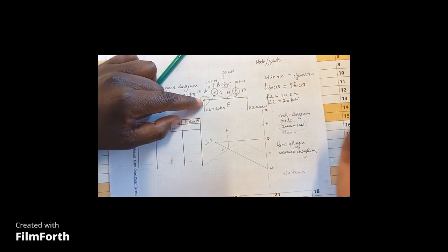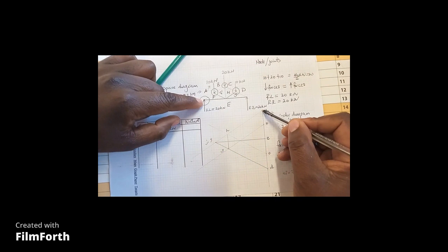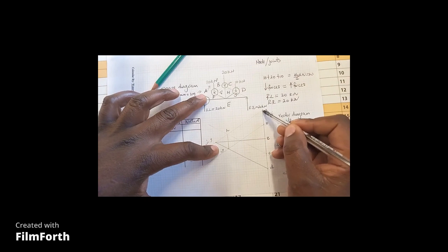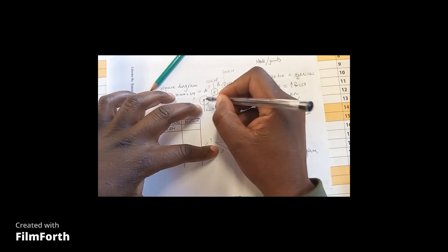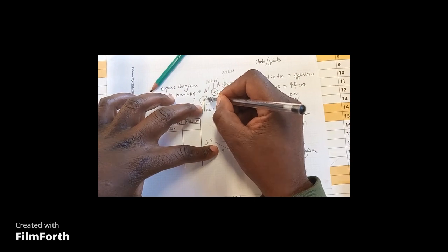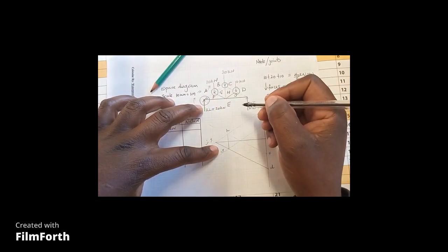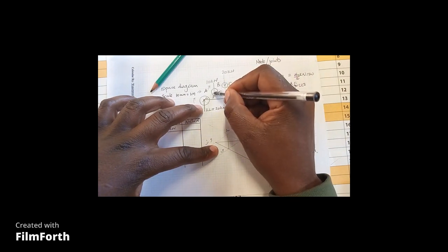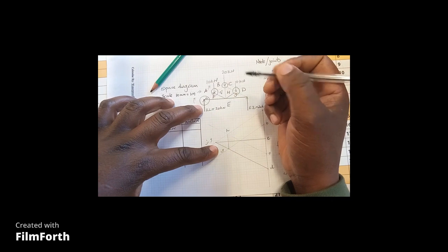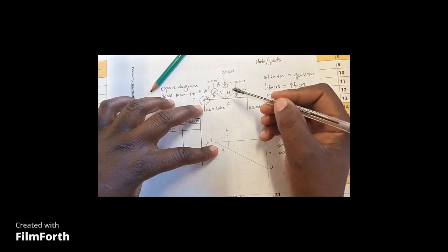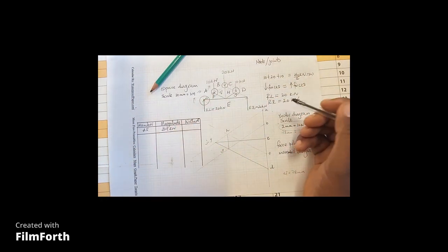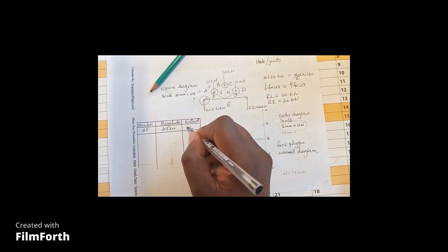I'll call it AF. So I check where is A, where is F. All right. Because I'm using this circle, I'm moving from A going to F, meaning I'm going down. So in this circle, you put an arrow going down. All right. And then right at the opposite circle, you put an opposite arrow. Obviously, this is according to Newton's third law, which says to each and every action, there is an equally opposite force acting to that force. All right. So this simply means that this member, it is a strut.